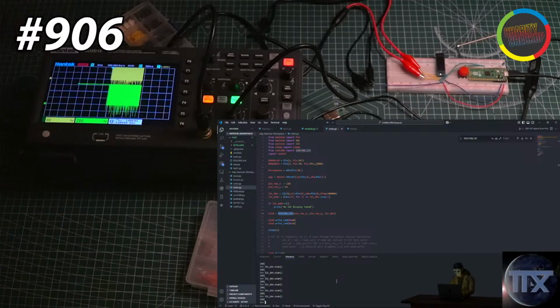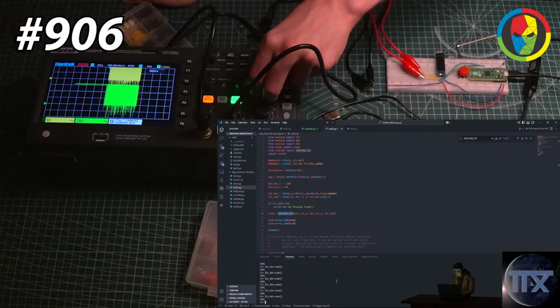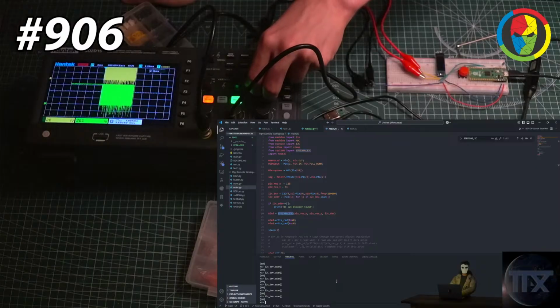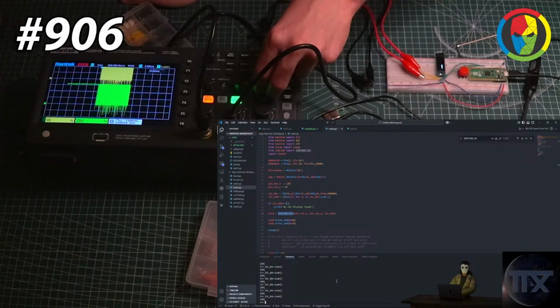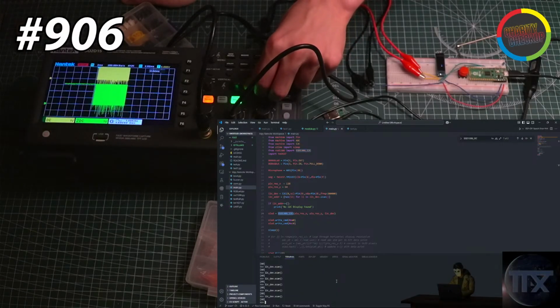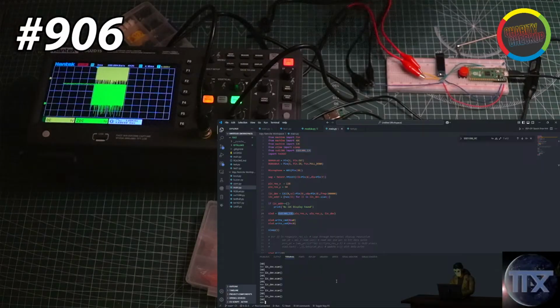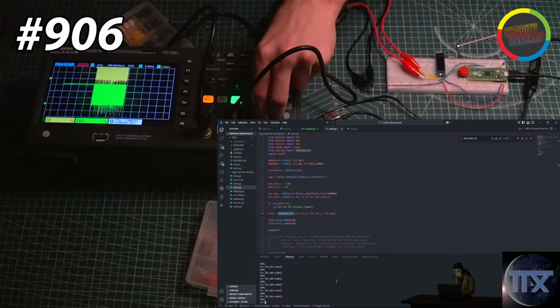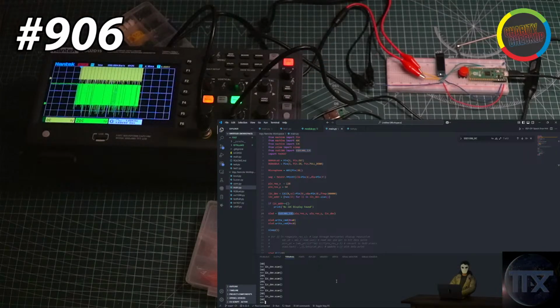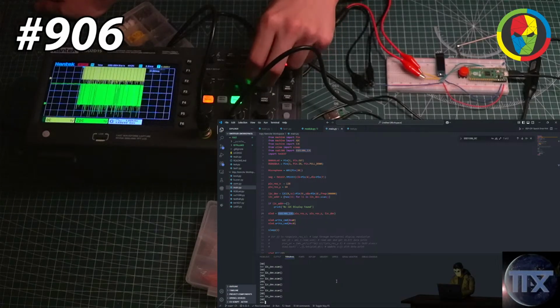When you adjust the knob to zoom in and zoom out, there should be text somewhere on the screen that changes, and it will tell you the width of each square. I can also move the face and see how far I need to. So it is in milliseconds. Move the zoom in and out, and that will tell you the width of each of those squares. Okay, so right now a square is a millisecond. Perfect. So then you can actually just calculate by counting the squares.